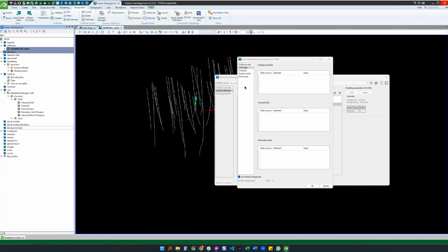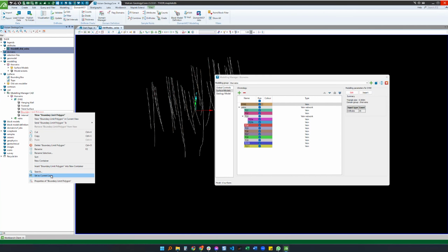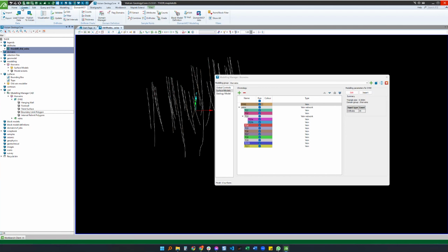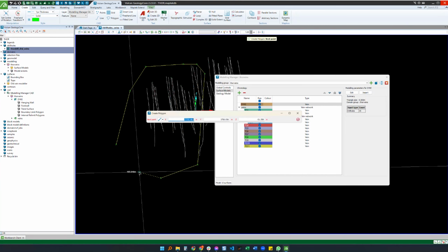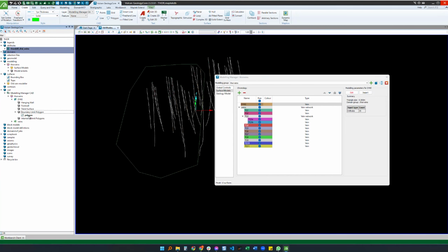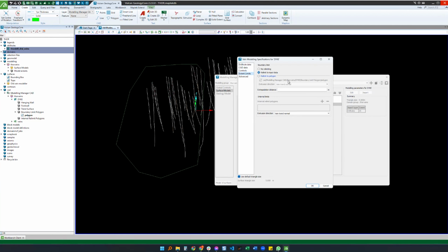All right, within that, each item has containers that relate to what you want to add data to for that particular thing, right? So if I close this panel, let's say I wanted to add a bounding limit or a boundary limit polygon for my dike. Right, I can right click on this and say set as current layer. If I start digitizing under my create menu and start digitizing a polygon, this isn't going to make sense, but if I do that, you can see that's obviously gone in there. Then if I open up my edit panel and go to my extent limits, you can see it's automatically picked up that polygon. So if I went relimit to polygon, it's going to use that polygon for me. Also, if I put stuff in the internal relimit polygons container, it's going to automatically pick that up.